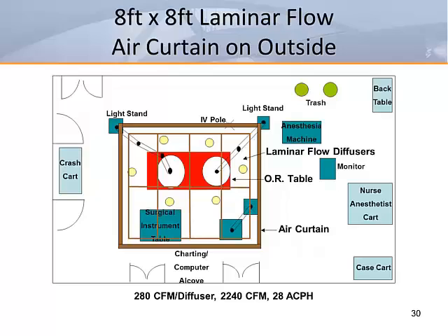To meet Standard 170 requirement, all that is necessary is the sterile field extending at least 1 foot from the sides of the operating table. As we discussed earlier, this would be about a 5 by 8 foot array. To prevent having the necessary operating instruments located outside the sterile field, we recommend extending the sterile field to an array of 8 by 8 of non-aspirating diffusers.